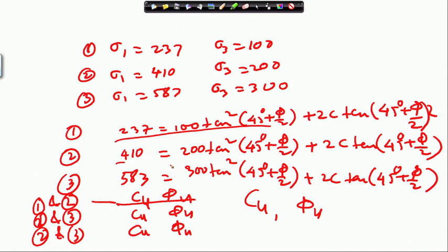So, a minimum of two tests is required, but the standard laboratory procedure is generally to conduct 3 or more tests, so that if there is any error because of sample preparation, equipment, etc., we can get the average values. We have plenty of data, 3 or 4 tests. You require only 2, but we do not know which is erroneous.